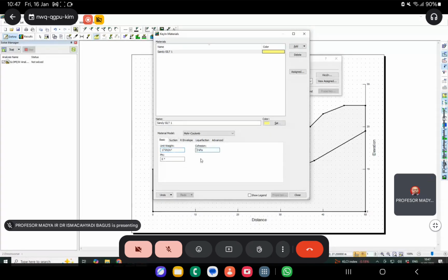Most practitioners will use an apparent cohesion value between 5 to 10 kPa, not more than that. But in my design consideration, if it is a high friction angle, over consolidated, I take 5 as a max.